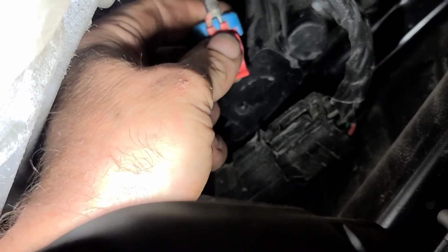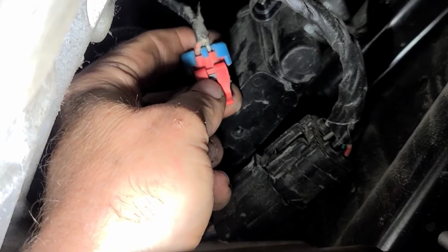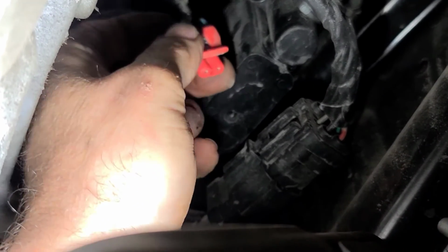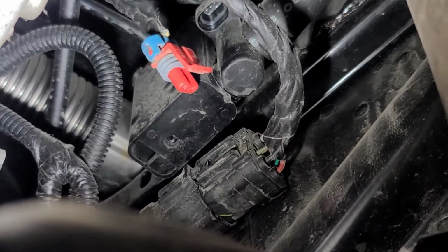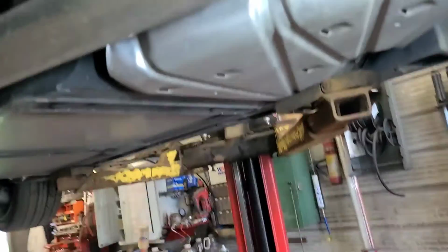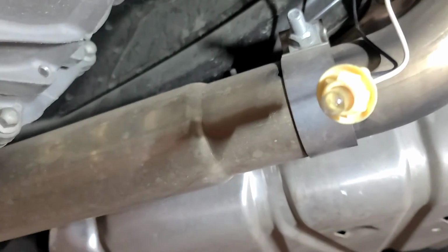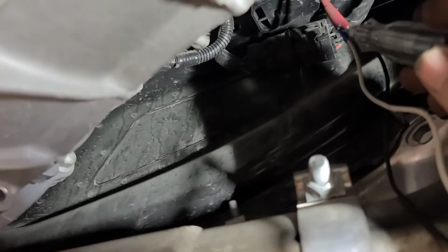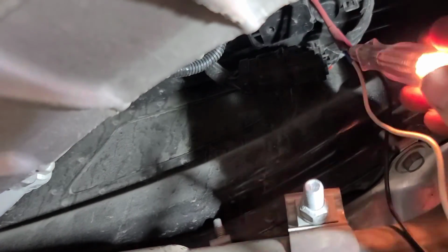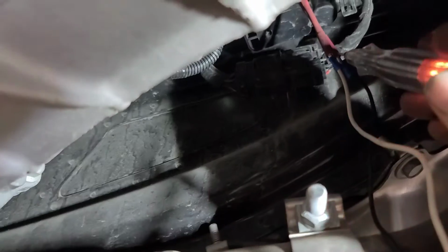That pink wire should be power, and the white wire should be ground side controlled. I'm sure that's the vent solenoid. Yeah, that's the vent solenoid. So I tried an alternate light just in case my Noid light had failed, and it's still not on. I do have power on this pink wire. You can see, and if I go on the control side, my light comes on dim and the test light comes on dim. So the wire's good up to there. My bulb is good.